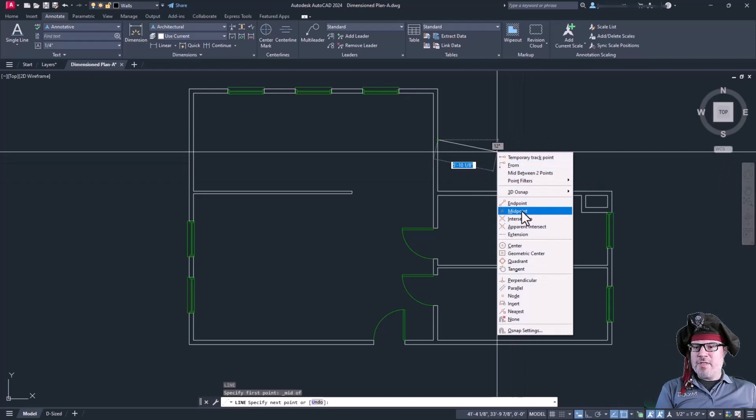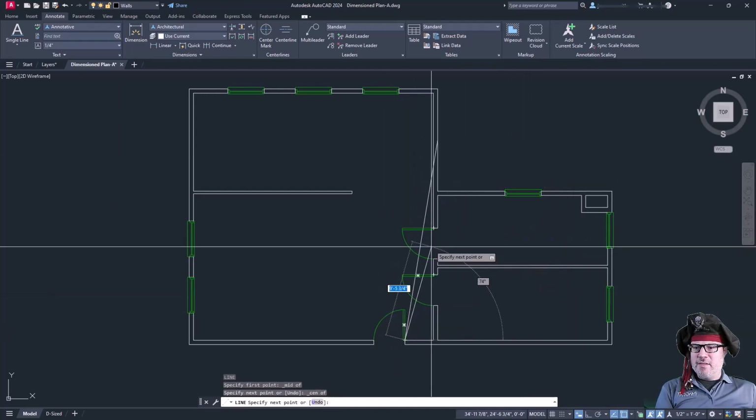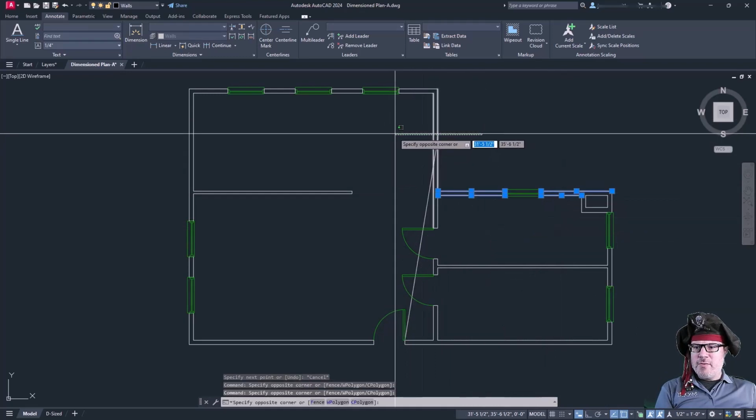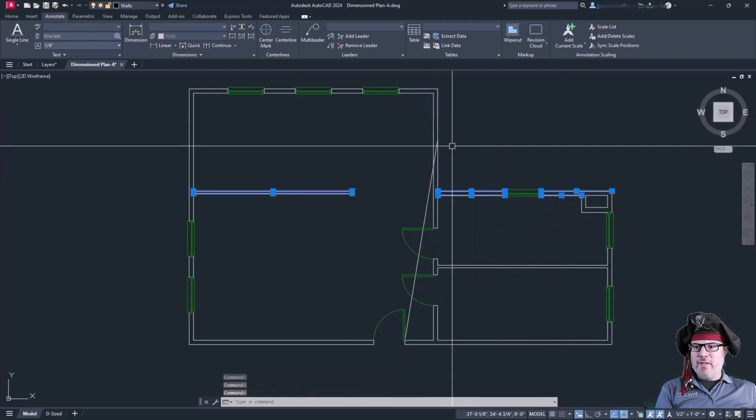Shift right-click. I can continue to use this process as many times as I wish. Choose center point, and only center points are selected. Left-click and it places the line, drawing it from one point to the next. When you are selecting content, continue to select objects one at a time. Hold down the Shift key and it lets you remove objects from the selection.